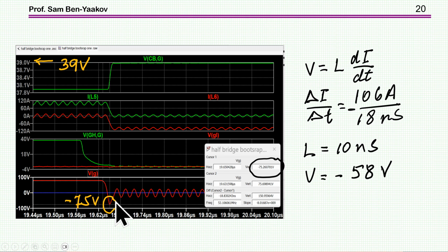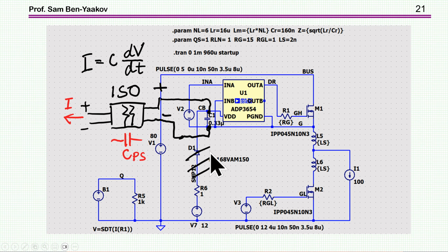Now why is this? Well, it is because this is a resonance circuit, and we know that its Q is higher than 1, so therefore there's an overshoot. So aside from this base voltage change, there is an overshoot to go to an even higher voltage. Now we are not charging the capacitor to this voltage because the time is short. You see, it's charging only during this short time, but still it got to a very high voltage, which is very dangerous. So what is the remedy for that?